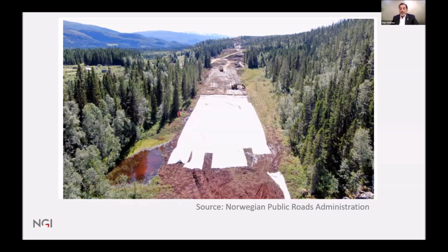So, very interesting. One of the options is to keep backfilling, but this is ruining the earth and very expensive, until you go to your first option, which is removing peat or compressing it to the max. Yeah, and that's what they did, unfortunately.